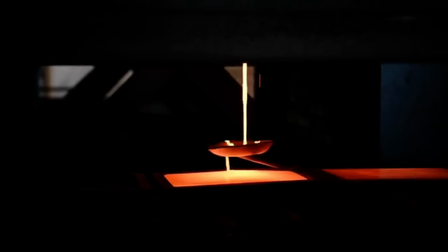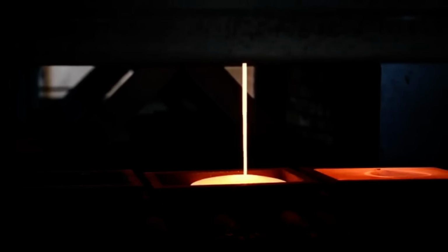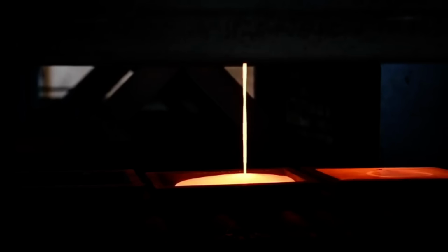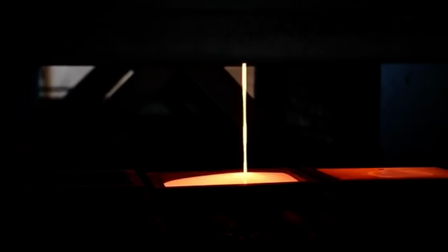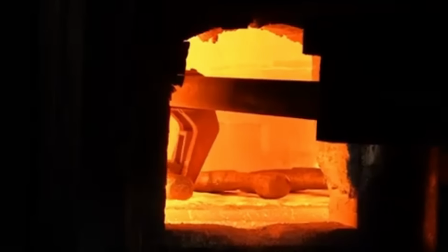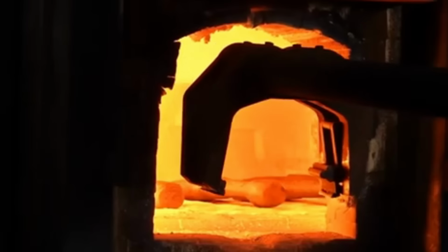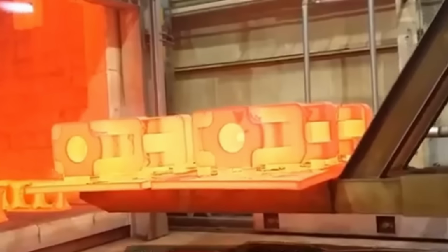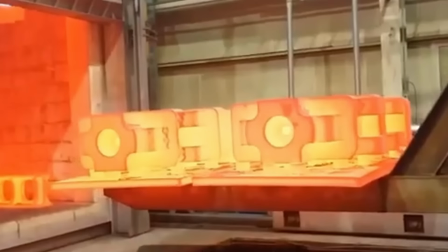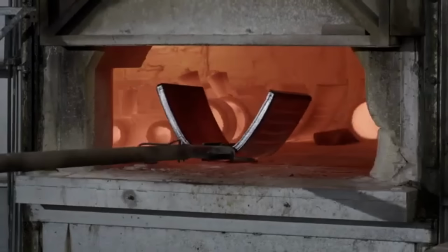Once we pour our cast, the next step is to anneal it. When you cool hot cast molds, the outside shell cools and contracts faster than the hotter core. That mismatch leaves residual tensile and compressive stresses locked in the body, which can cause flaws. Annealing is simply holding the cast at a certain elevated temperature long enough that temperature gradients equalize, then cooling it very slowly. This relieves the internal stresses and brittleness and improves its mechanical and thermal performance. The industrial standard for cast basalt is to put casts in a layer furnace, cooling them slowly from 800 degrees Celsius to 50 degrees Celsius over the course of 24 hours.